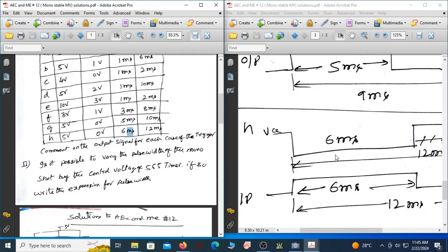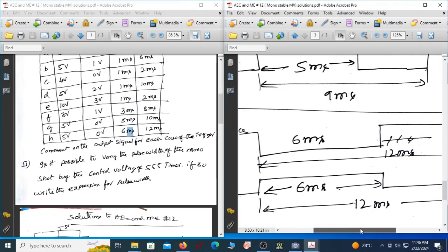If it was passed through the signal conditioning circuit, then I would have got a pulse width of 4.392 millisecond, whatever the time designed. Since it is not going through it and stays less than VTL up to 6 millisecond, the output is 6 millisecond, beyond the pulse width of 4.392 millisecond.